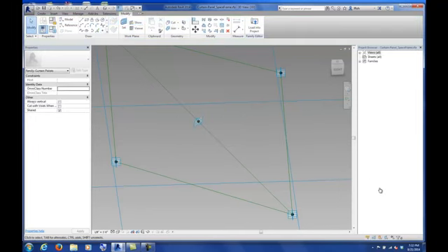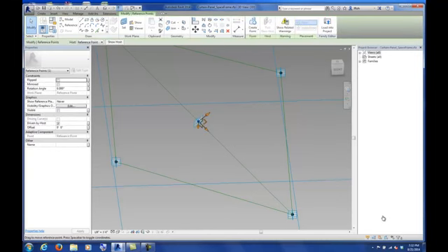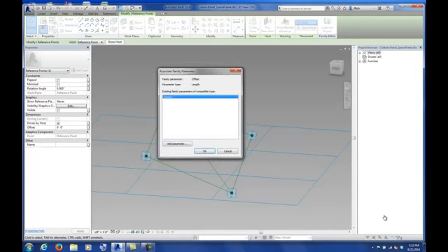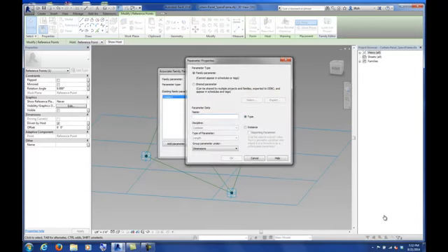Now what we can do is I'm going to select that point that we just created. And you should know that you selected it because you get these orange axis grab bars to actually move this point. But off to the left it says offset under properties. I'm going to click on that button, and we're going to make a parameter here called space frame depth.